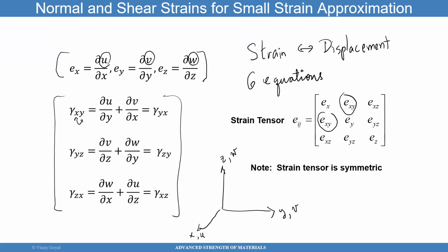And then I have 3 deflections, but then I have 6 strains: 1, 2, 3, 4, 5, and 6. So right there, you can see I have 9 unknowns. So I have 6 strains, 3 displacements, but 6 equations. So I have 9 variables total, but 6 equations. So something's missing here, as you can see. I need to have an equal number of unknowns and equations.